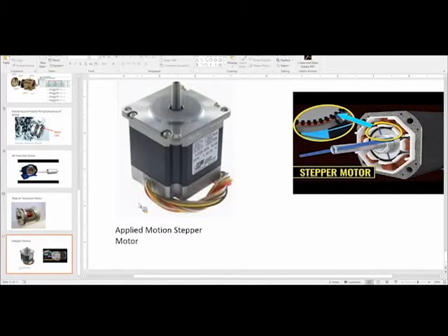The rotor is made of a stack of steel laminations. It has a different number of teeth than the stator, 4 in this case. This is done intentionally so that only one pair of rotor teeth is aligned with the stator at a time. You can explain how this stepper motor works by yourself.